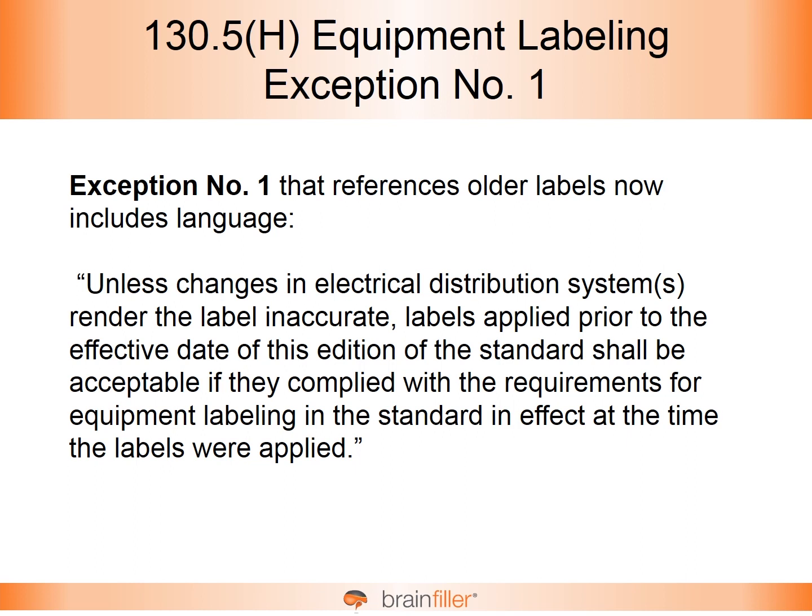Well, a couple of the main things would be if perhaps short circuit current changes from the electric utility company. That may have a minor effect, but if it's a major change in short circuit current that has a significant change in the incident energy, that may ultimately affect the arc rating of the PPE. Or perhaps protective device settings changed, or maybe transformer sizes were changed.